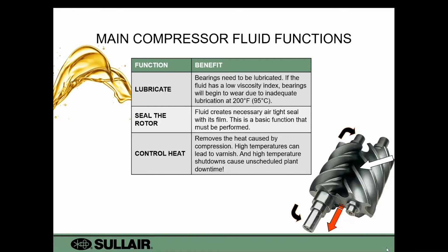And third, you need to control the heat. A lot of heat is caused by the compression of the air. We want to make sure we dissipate that and keep our temperatures under control, because once you start pushing above 200 degrees Fahrenheit, you can have issues with viscosity. You also shorten the fluid life as well. So these are the three main things it must perform on.